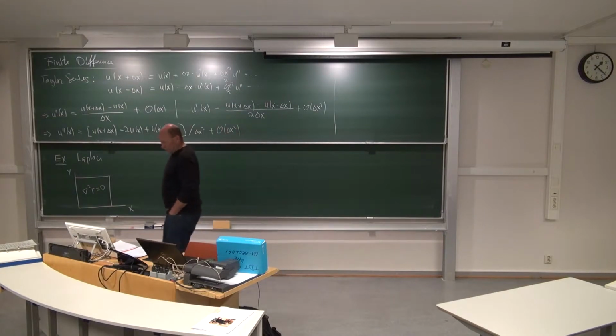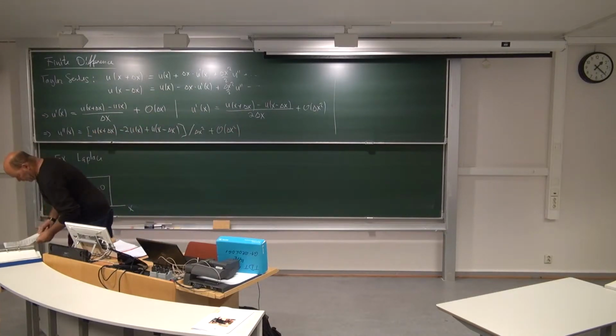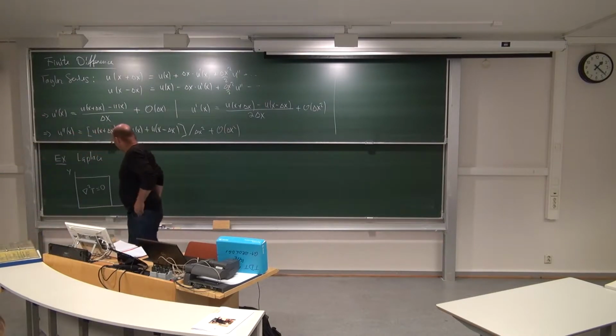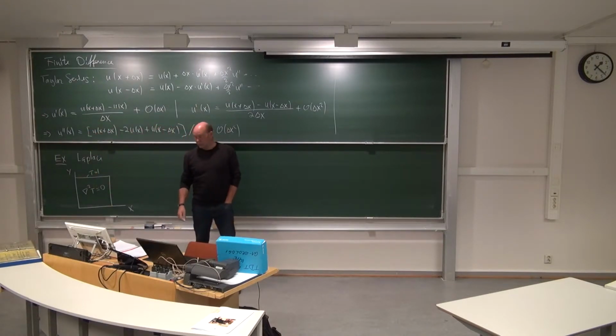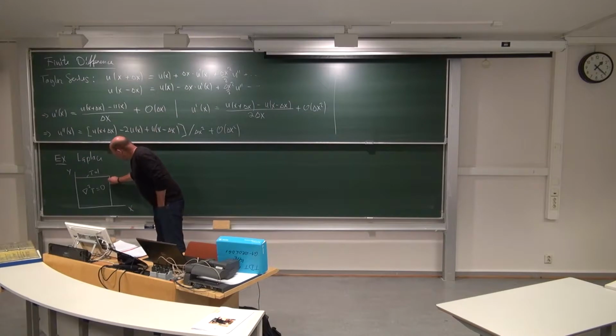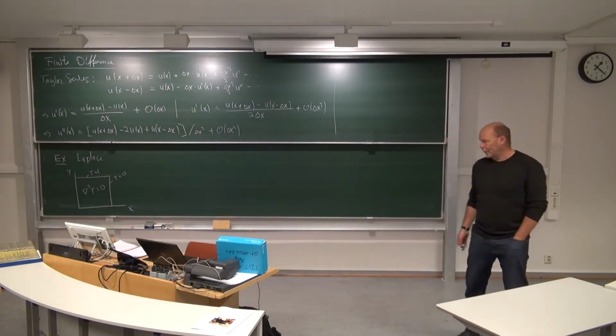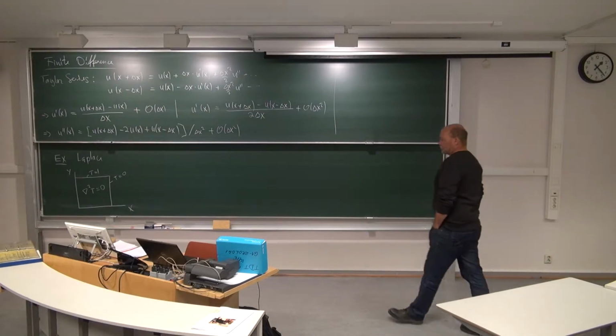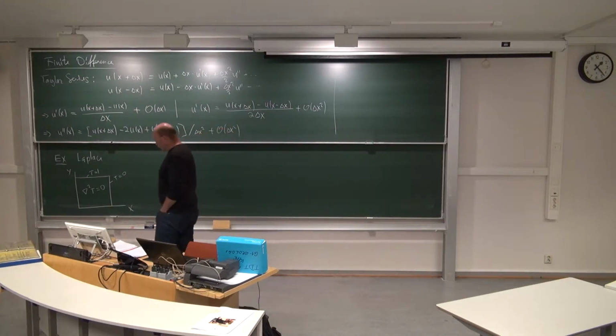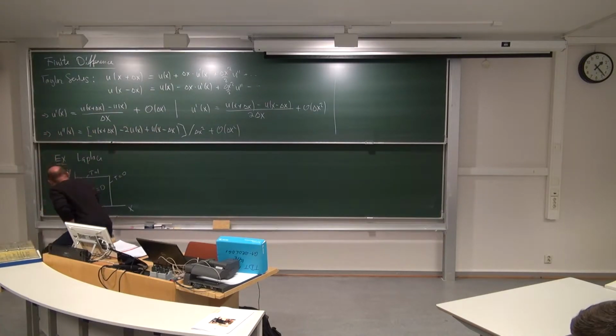Then we need some boundary conditions. Here I have chosen, let's see, the top wall here, he is hot. Temperature equals 1. The right wall, he is cold. So those two we call Dirichlet condition. You give the numbers directly. The 2 other walls, there we use a Neumann condition, derivative equal to 0. So meaning they are insulated or something.